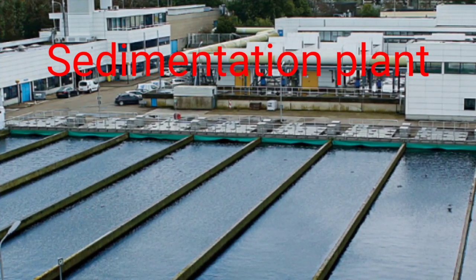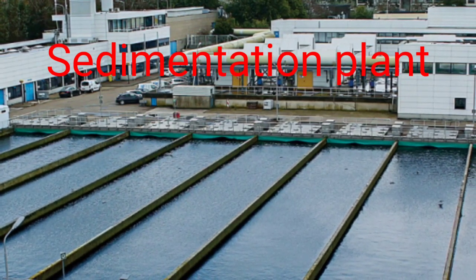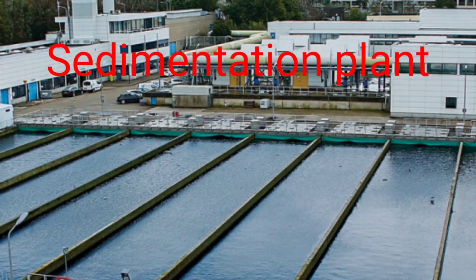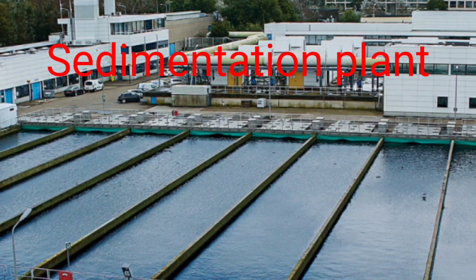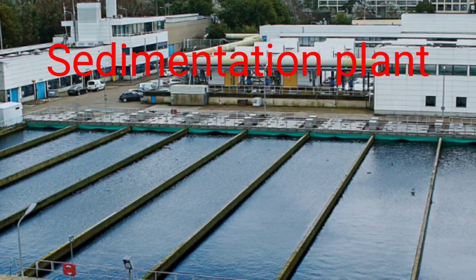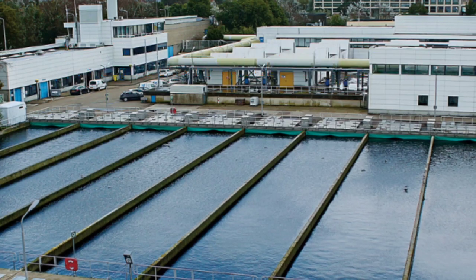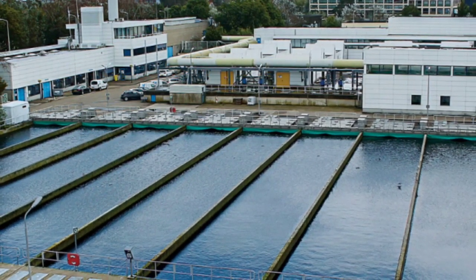The efficiency of performance of the process is controlled by the detention time, temperature, tank design, and conditions of equipment. Most treatment plants include sedimentation in their treatment process. However, sedimentation may not be necessary for low turbidity water of less than 10 parts per million. After the sedimentation process, the water is transmitted to the filtration tank.